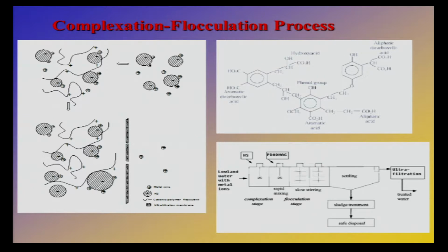So you see here that the charges in this whole system will neutralize, just like we saw yesterday. The charges neutralize, but now you see that these very large molecules can bridge between the particles. So this is the kind of polymer bridging. We get something like this. So humic acid, heavy metal, and then here is the polyelectrolyte, and it's kind of joining all these dots together.